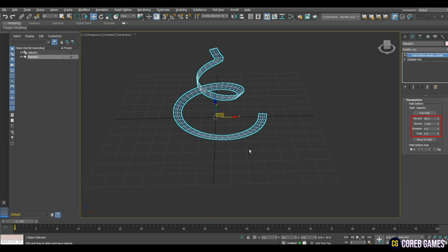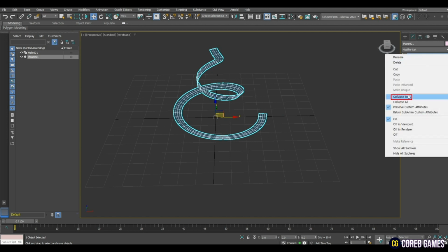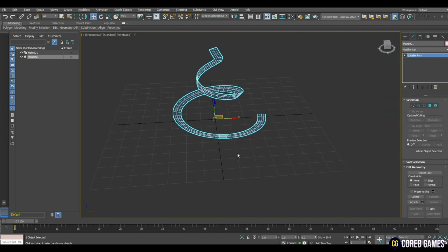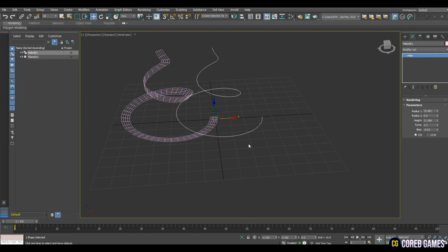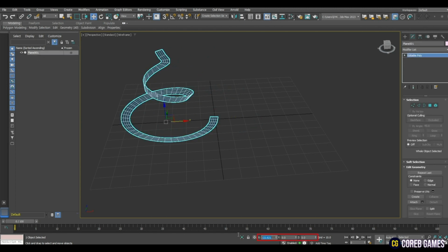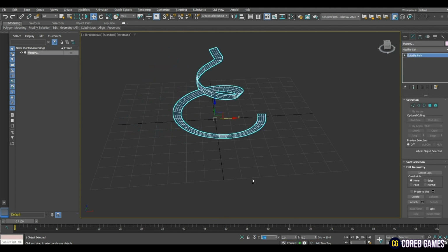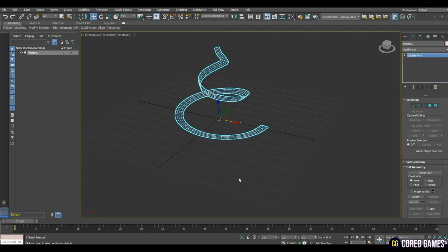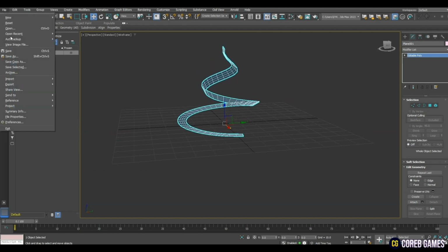When the desired shape is created, press Collapse 2 to create the final mesh and merge them. Finally, remove the helix line that was made at the beginning and place the completed mesh at the origin. Click Export Selected in the File menu and save it.